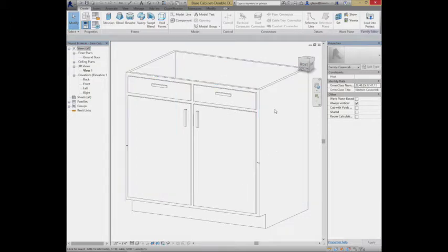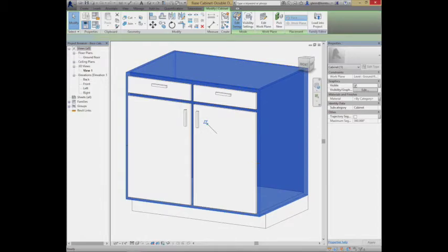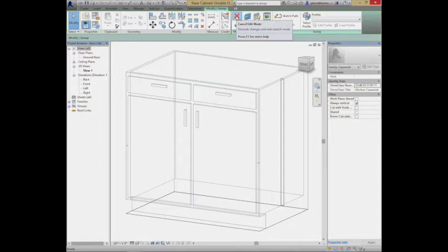And if I hover over something, you can actually see, well, that's interesting. It's considered a sweep. It looks like that might have been able to be done as an extrusion, but let's think about how it got defined as a sweep. I'll choose it, and if I say edit the sweep, we can see that's interesting. It is a boundary. It's sweeping around, and it's just this tall rectangular profile that's going around.